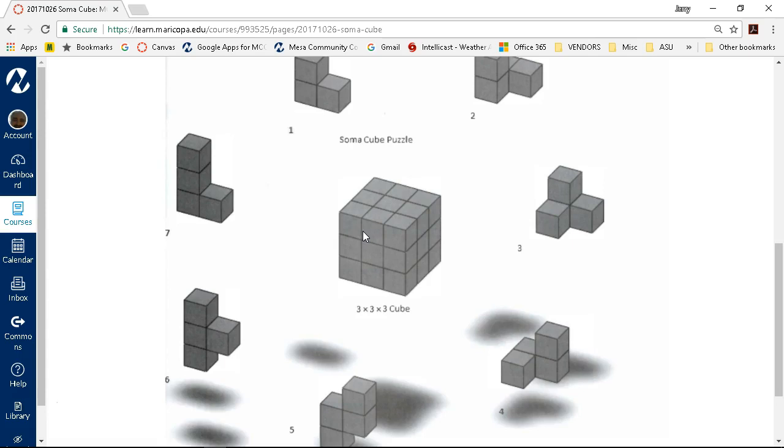If our intent is that this be dynamic, probably not that dynamic for the puzzle, we just want to put it together. But if we want it to be dynamic, then we're going to allow one of those degrees of freedom to remain underdefined and cause the movement. That is not the same as creating an exploded view.